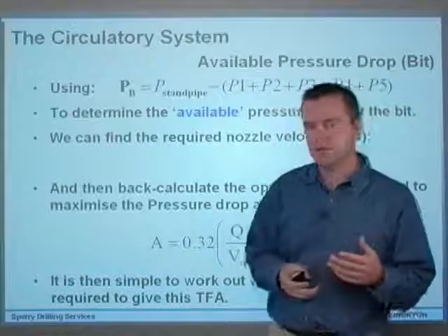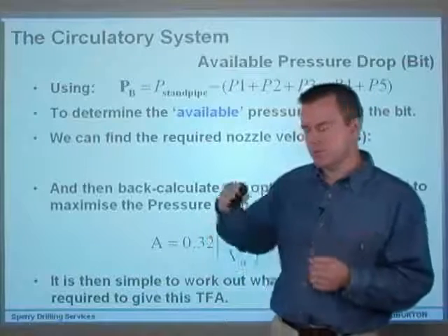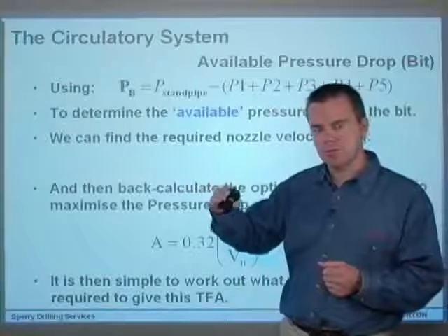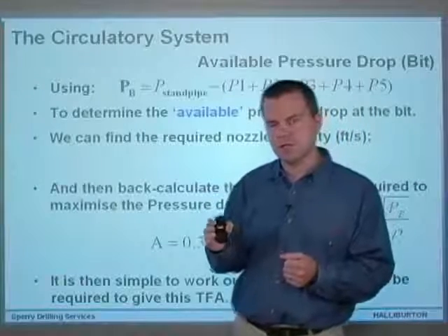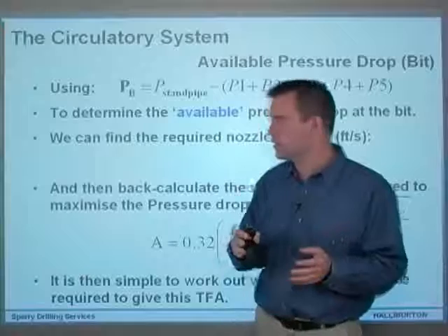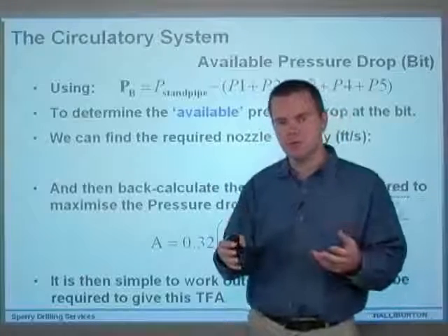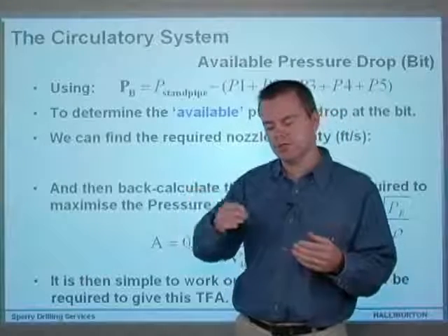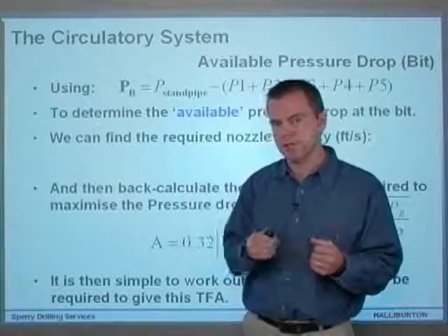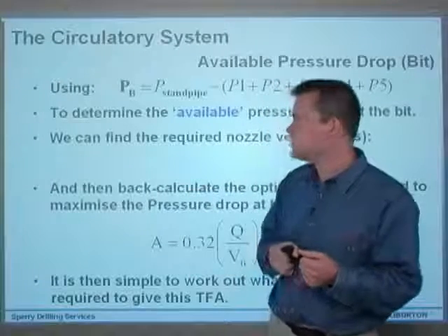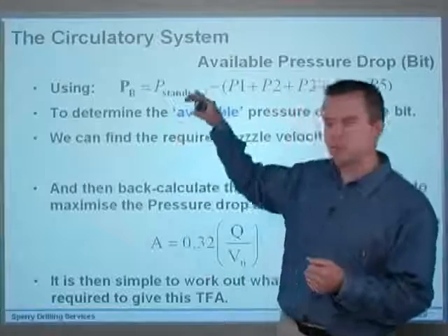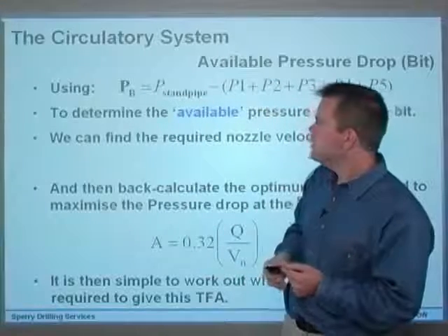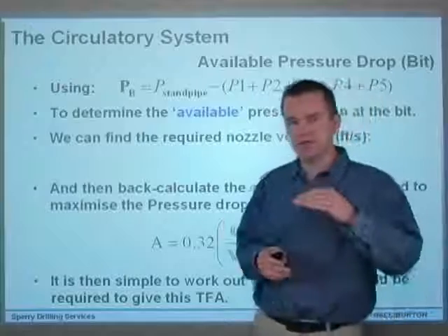And usually your pump manufacturer will give you a value that's the maximum pressure that the pumps can hold. In general, most drilling engineers, when they're designing the overall wellbore, would only really want to go to about 80% of the maximum standpipe pressure. Certainly the guys on the rig would only want to go to about 80% of the maximum standpipe pressure. So that would be your limiting factor.